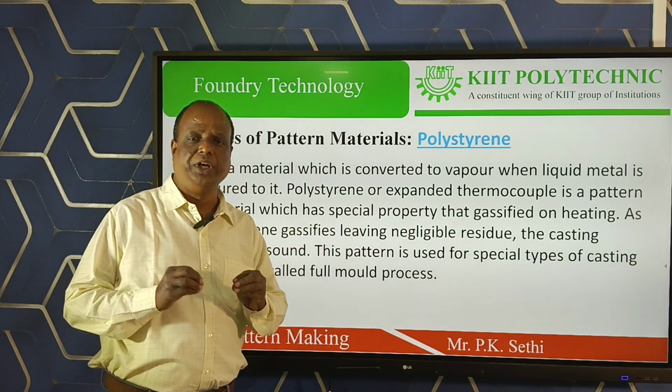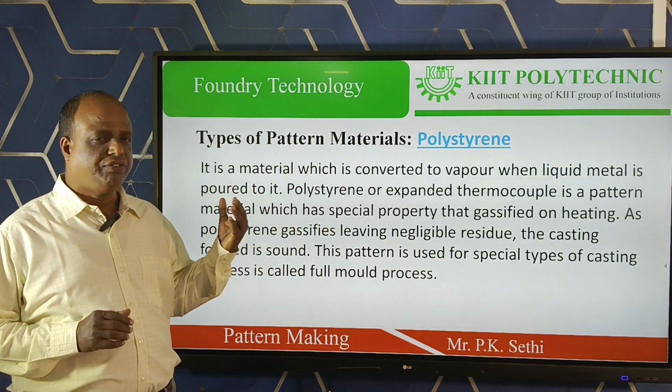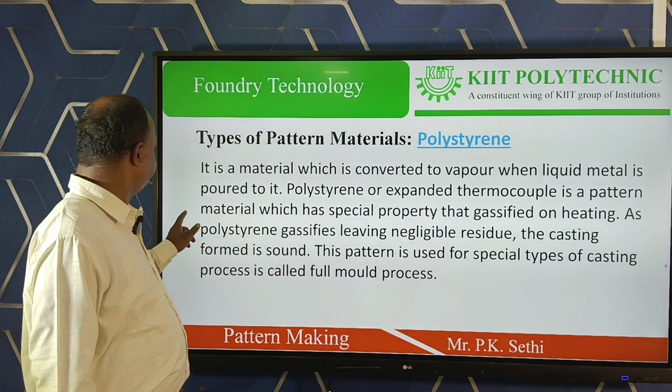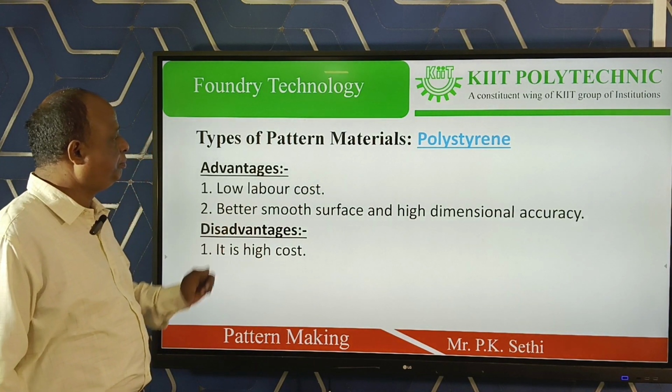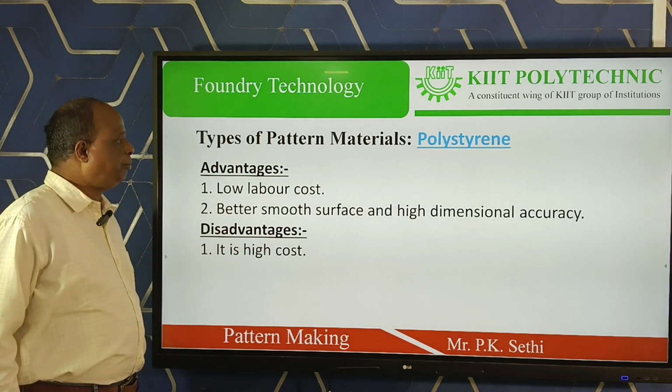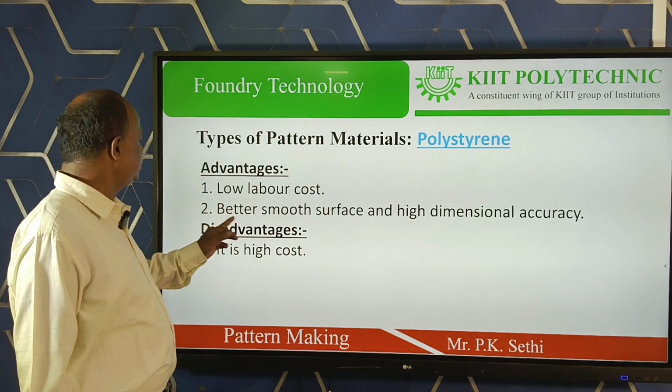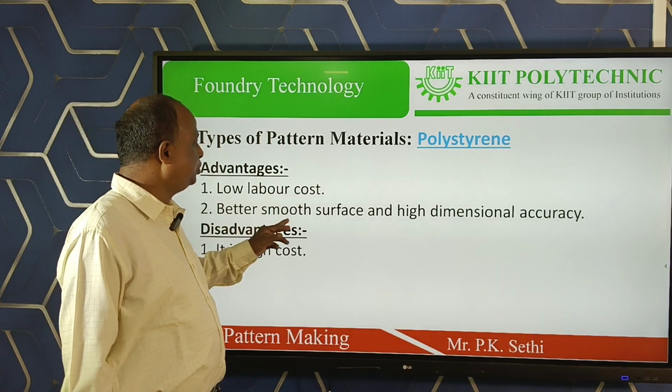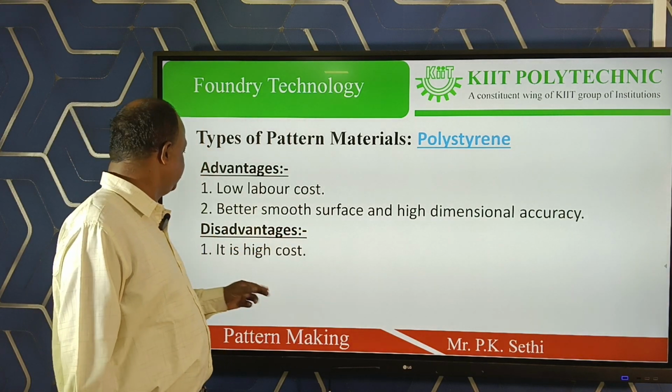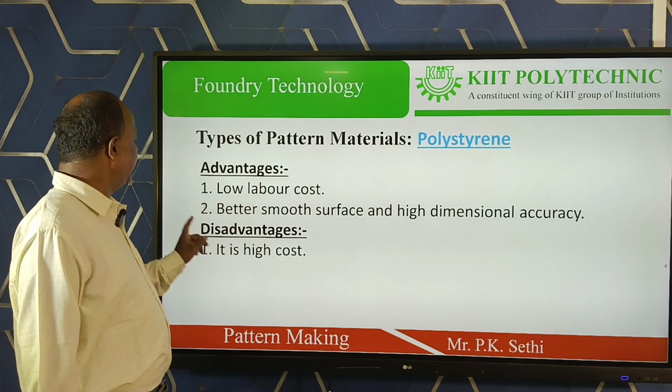Sound means there is no defect, unlike other pattern materials. So these are the advantages of polystyrene materials: number one, low labor cost. Number two, a better smooth surface and high dimensional accuracy. And the limitation is that it is high cost.